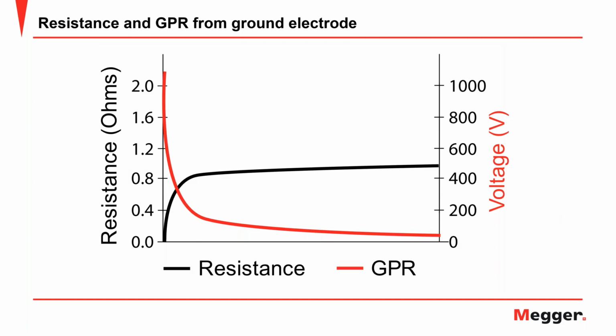And this, for those of you who like graphic representations, just portrays the same idea in a graphic form, the idea that as your current goes to zero, your voltage rise levels off and becomes steady. And as I said, in the case of safe ground potential rise, you want to keep that below at least 50 volts and maybe 40 in some more rigorous environments. Next.